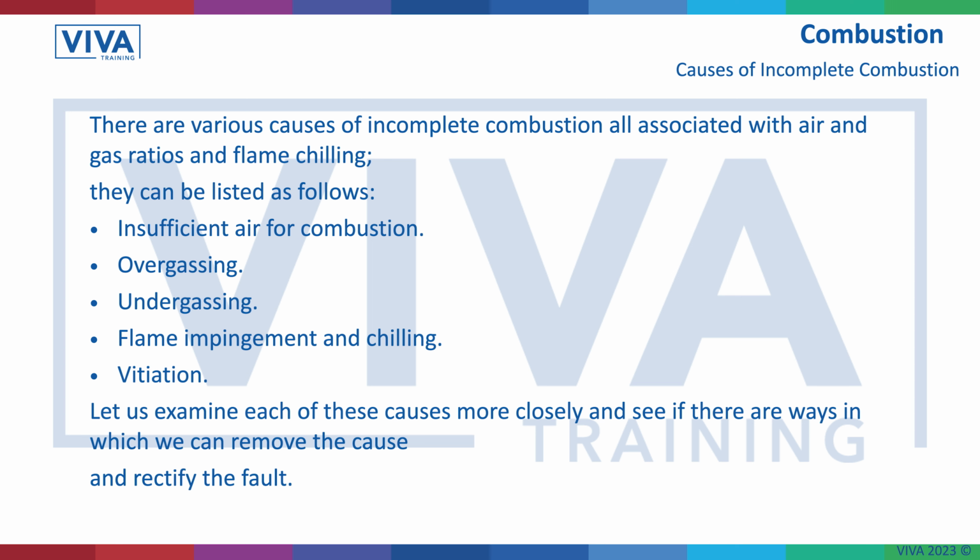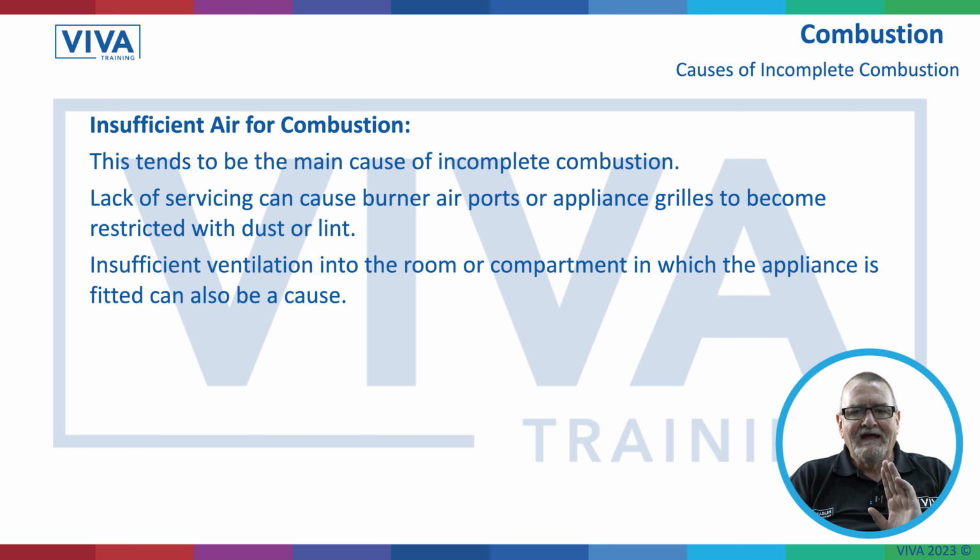So let's have a look at each of these in more detail, just to give us a better understanding, and then we can look at how we would rectify this. So, insufficient air for combustion. It tends to be the main cause of incomplete combustion. This is the biggest cause that me and you guys will go out to if the appliance isn't burning correctly. The main cause is lack of servicing.